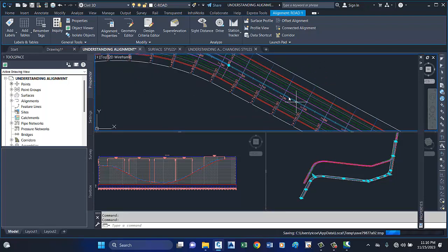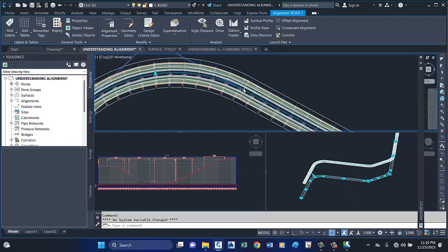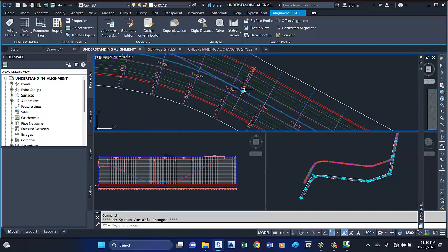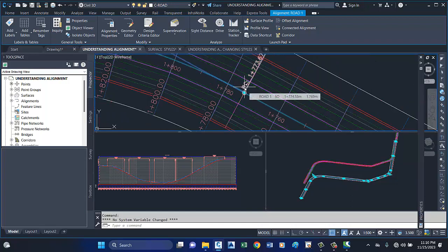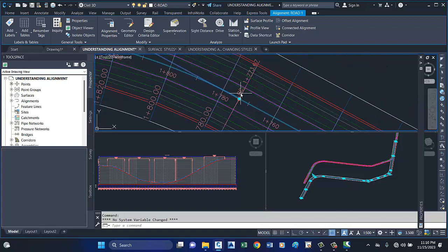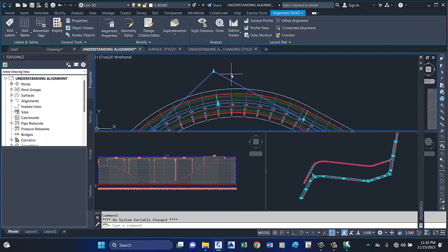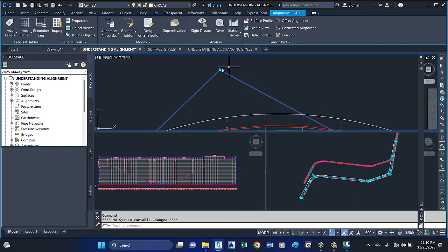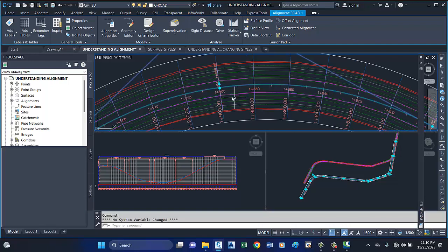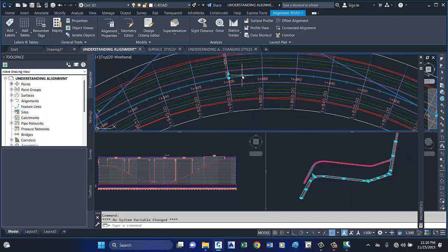They compose lines and segments. The point where the start of your curvature is called the point of curvature, and the intersection of the two tangents is called the PI, and the midpoint of the curve is called mid curve.